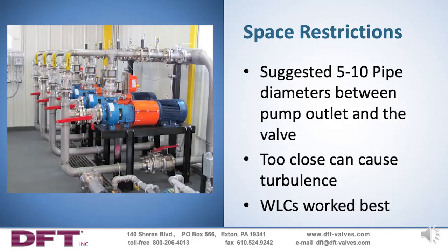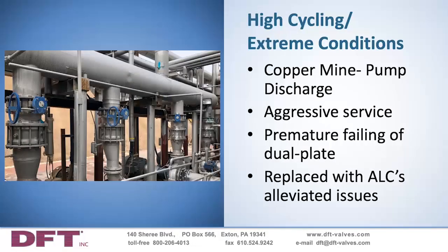Here I'm going to talk a little bit about some high cycling and extreme conditions that can be found out in the industrial world. In this slide, we're looking at a copper mine with pump discharge. It was a very aggressive service, and the dual plate valves that were installed were failing prematurely. In fact, some of the valves installed in this system were also wafer-style swing check valves. These valves were replaced by the DFT model ALC check valve.